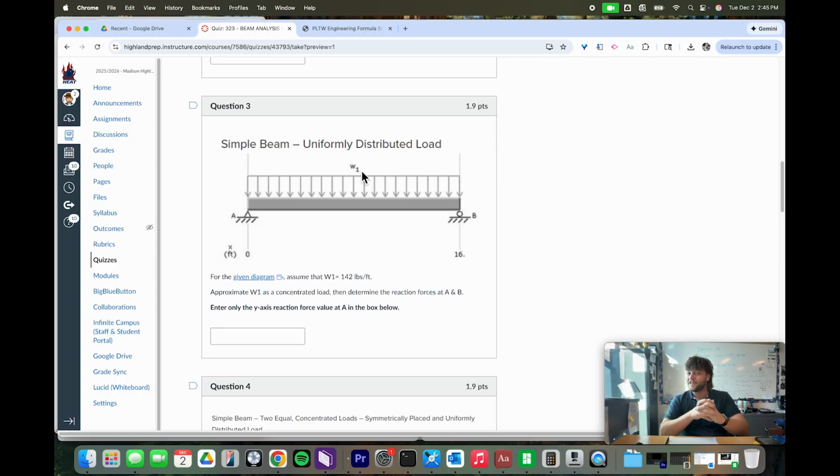And so this uniformly distributed load, remember, we calculated that out in activity 3.2.2. The uniformly distributed load is equal to your tributary width multiplied by that total load that we end up finding. And so remember, the total load equation is from the IBC, the International Building Code. We were using the 2012 edition. Usually it's dead load plus live load or the snow load. But anyways, that's where we're getting W1, just so you guys make sure that you don't get too confused. You're like, what is W1, you know? But this is what it ends up looking like on the beam, that uniformly distributed load.